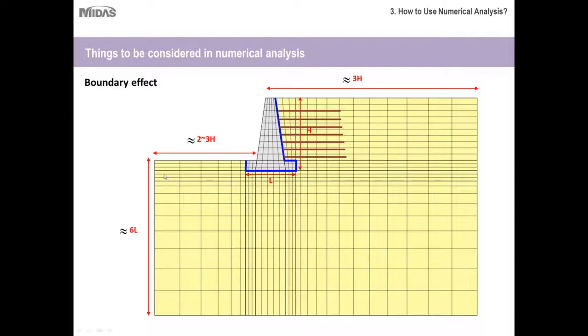When you are looking at the results, if you see the stresses are not zero at these ends, but rather have some significant value, and you can see through contour plots, you would have to take a bigger boundary until you reach a point where you don't have any more stresses at the outermost boundaries of the soil strata.